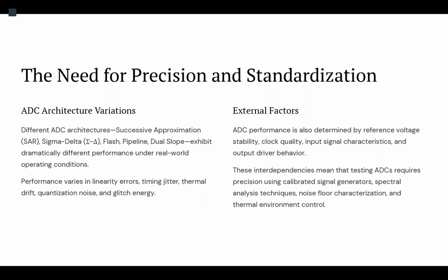Therefore, testing of the ADC must go beyond the architecture. So we have to consider reference voltage stability, input signal, or clock accuracy. And environmental factors, because temperature or ground noise also significantly affect the performance of these tests and the ADC behavior.